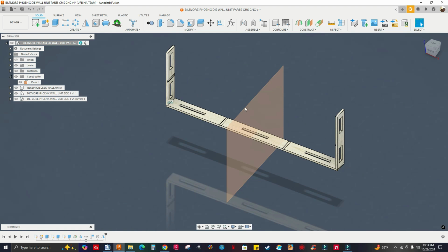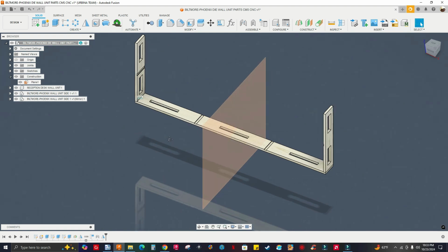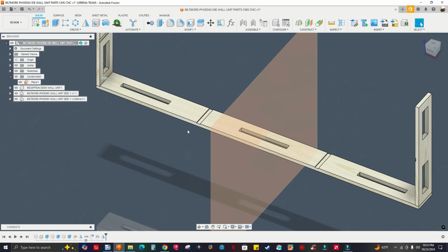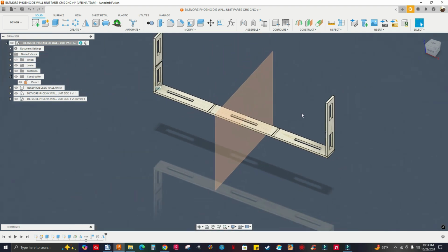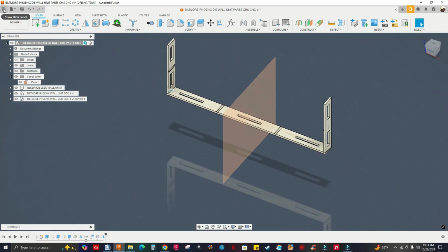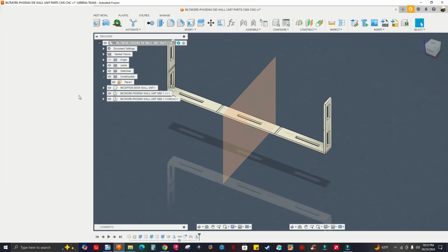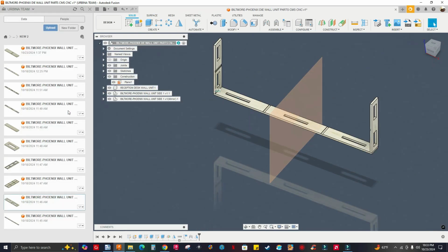And I'm going to leave this on because I've got to mirror the dividers, the little pieces that go here into these two grooves. So I'm going to show the data panel. I'm going to look for that divider and this piece right here. Sometimes you have long names, you can't really see what it is. So just hover your mouse over that, and it's going to tell you what it is. Like okay, so it's a divider. See the word at the end. So it's this one with drag and drop, right?